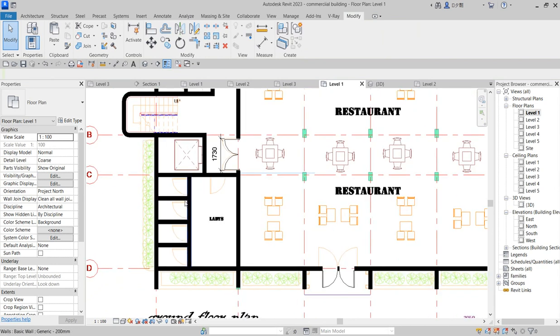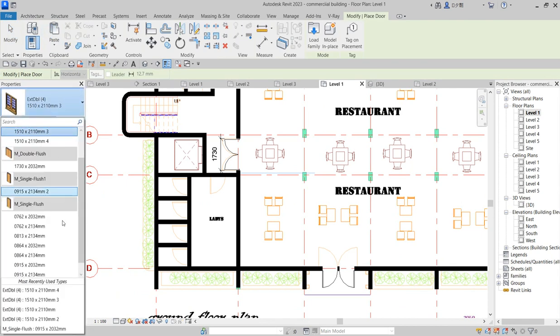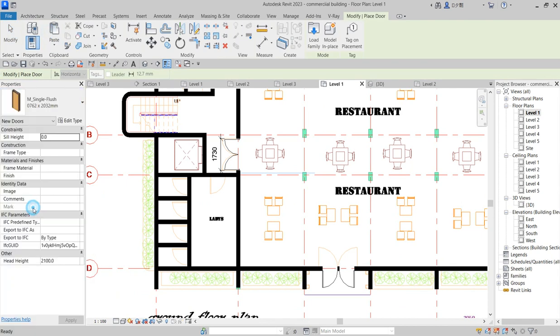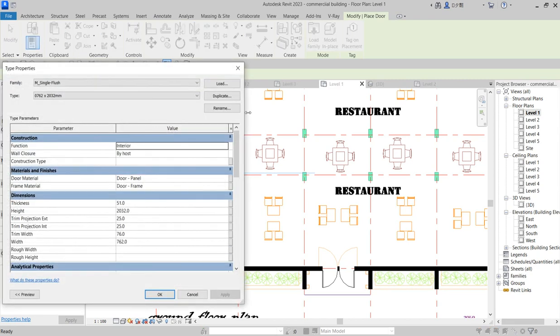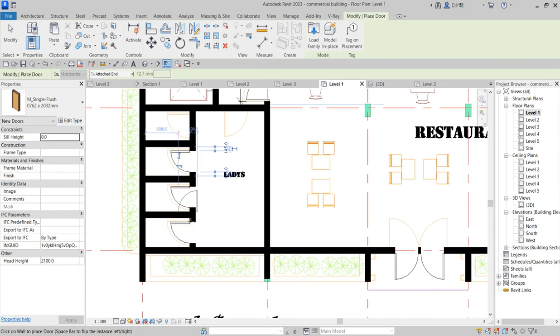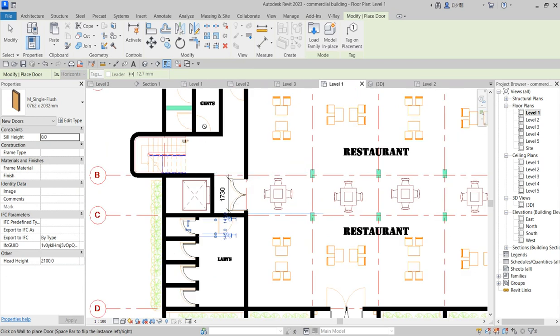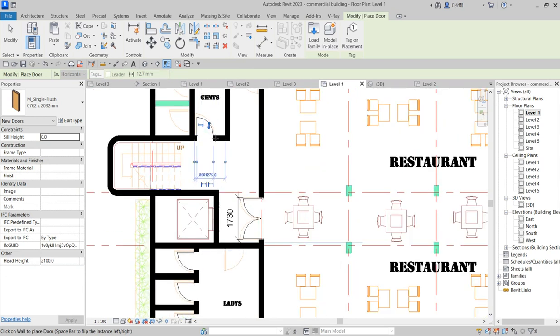So as we have done this one, you can now bring the toilet door into space. Click on this, go there, then you select the toilet door from the array of doors that you have here. You click edit. So you can decide to duplicate, or since there are many, just use a particular one. You can change the height to 2100, and that is how you pick that into place and start to fix them where you need to fix. So you do that for the whole toilet. That's how you trace everything one after the other till you get to the level that you need.